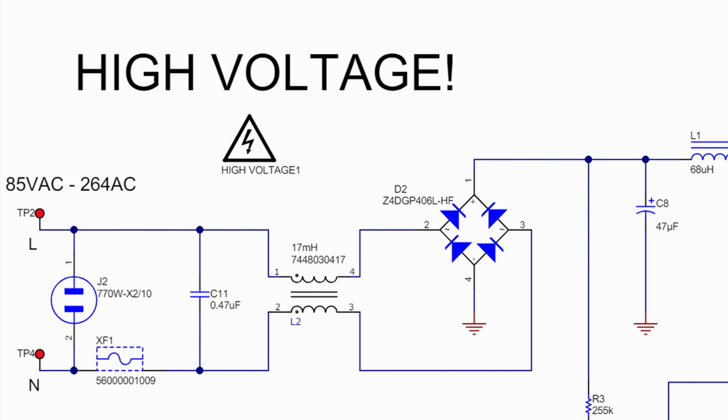While it is very similar to the input capacitors of other converters like the buck and boost converter, there are some key differences that I want to talk about. One is the input voltage rating. See, flyback converters are usually designed for offline applications, meaning they receive their input voltage directly from the AC mains, aka like your wall outlet. That means your input capacitor's voltage rating is going to be substantially higher than with other typical applications.